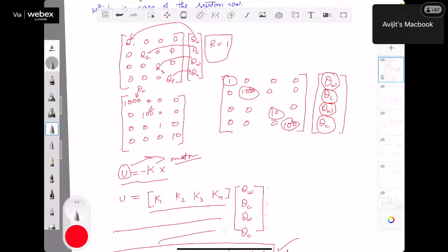Although we represent them separately as P, I and D, they are all intertwined with each other. So if we change KP, KI and KD must be tweaked a little. And that is where a hit and trial game starts.